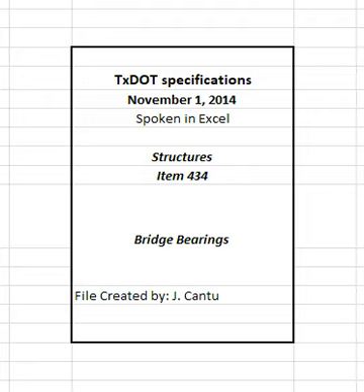2.1.2 Steel laminates. Provide steel laminates, for laminated bearings, of commercial grade steel strip or sheet with a thickness of 0.105 plus or minus 0.015 inches. 2.1.3 Steel top plates. Provide steel top plates, when required for laminated bearings, in accordance with the plans. 2.1.4 Special components. Provide steel guide bars and bottom plates, when required for laminated bearings, in accordance with the plans.